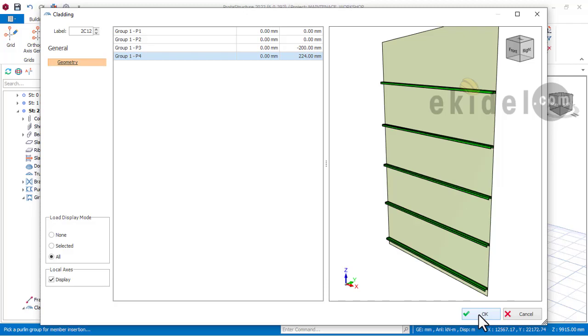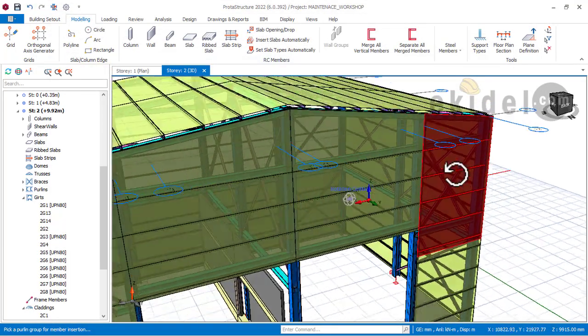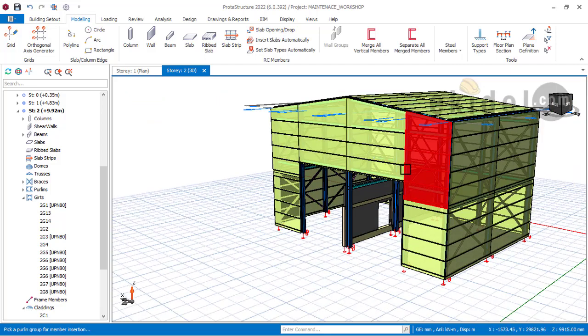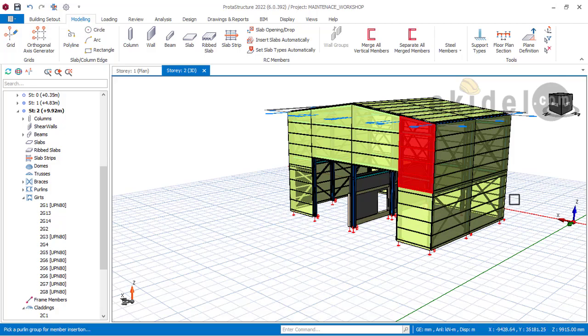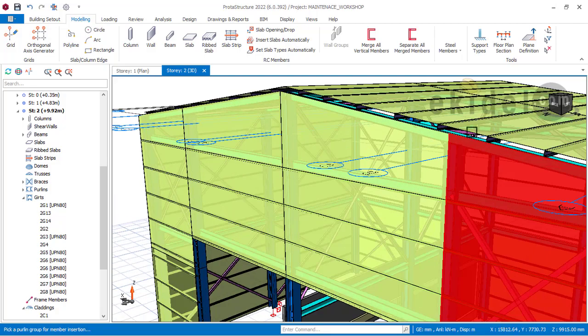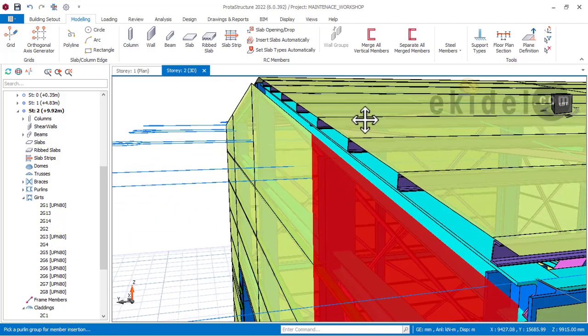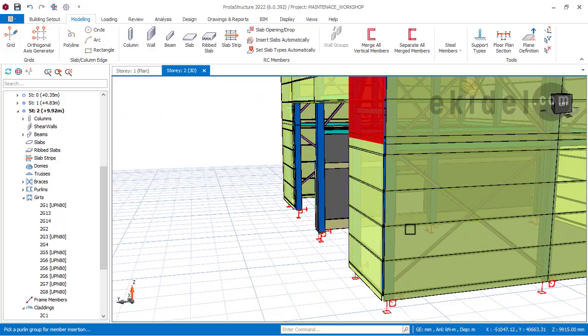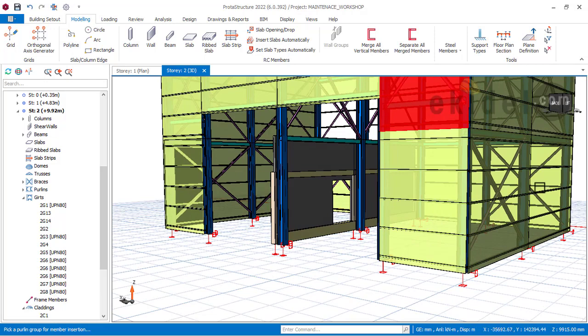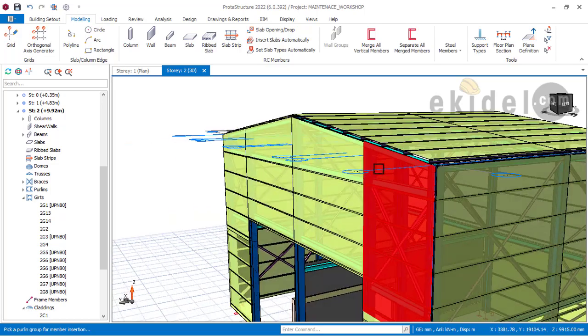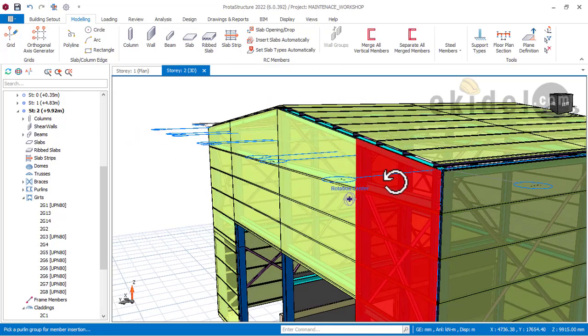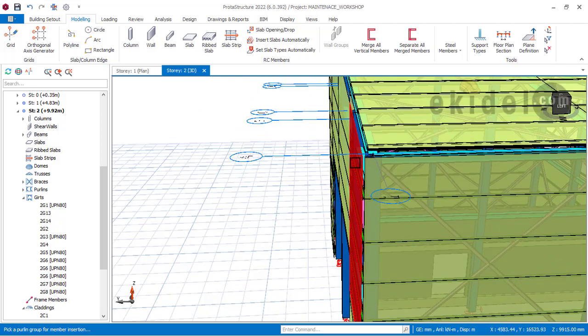Okay, I'll now come here and click on okay, and then you will see that it will just fit into what we have here. So you can now see how we have created a cladding for this upper level, which is different from how we created the level for this lower one. The reason is that this upper one requires a slope to work with, and you must work with the slope while you are putting in your cladding. This is different from what we were doing before here, because that other one is just a simple way of putting cladding that does not require any kind of different level or slope. But this other side requires you to work with that level before you can fit in your cladding, based on the shape of your steel structural modeling.